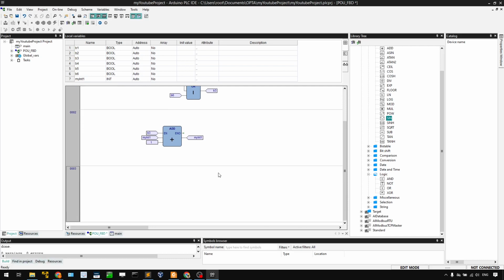For example, some options or commands will only run from a signal that goes from false to true, or from true to false, and then get back to false again. It depends on what kind of application or drive you're using. For example, if you're using Siemens, you're using the function block. For the S120 drive, the servo on signal only accepts a false to true rising edge.